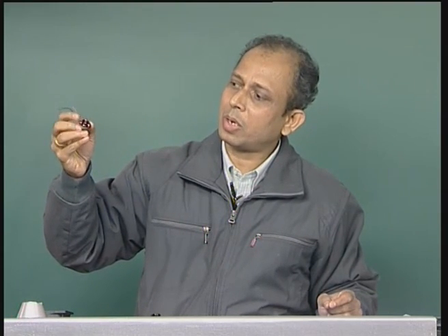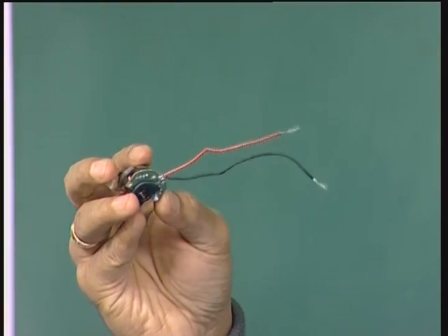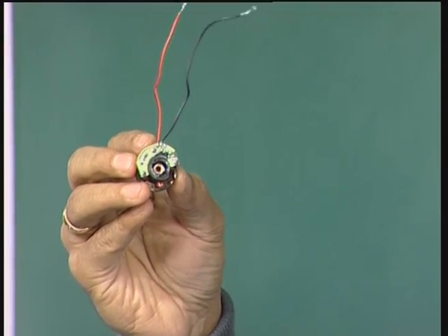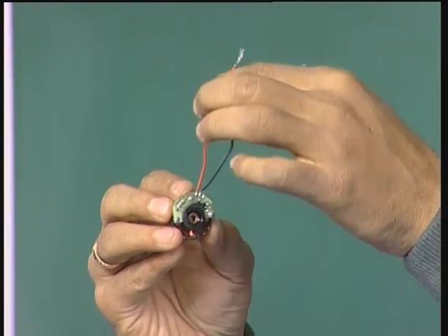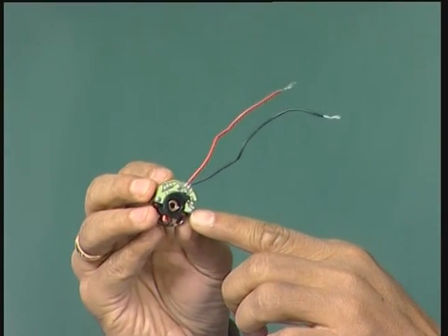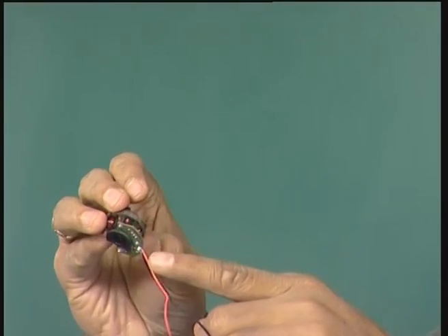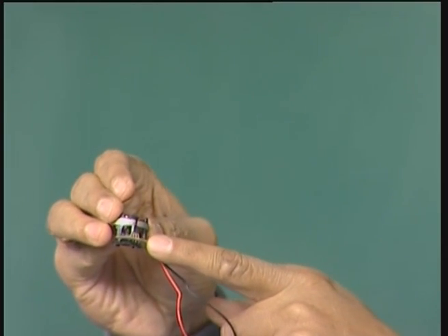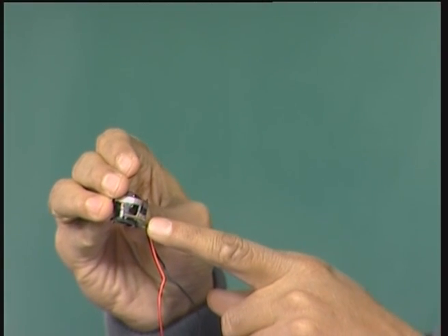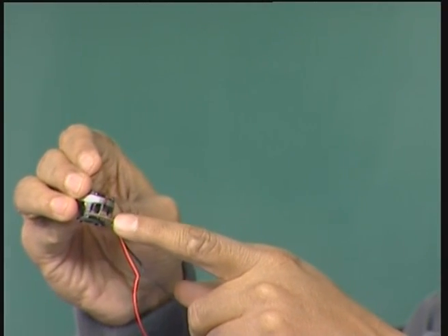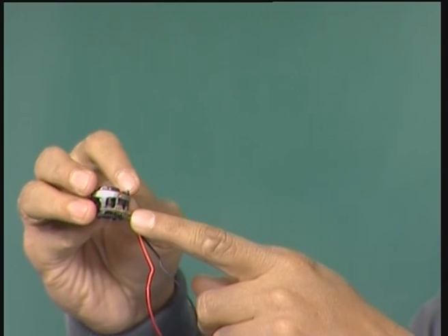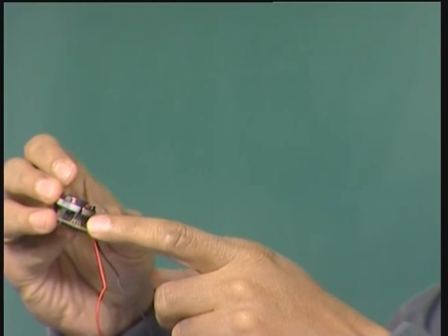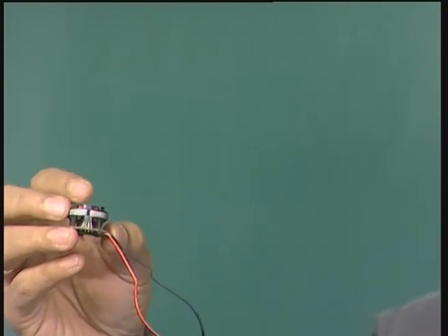And if you see very closely, there is a printed circuit board here which is attached to this stator. It is stationary and connected to the external power supply. So, this is the printed circuit board, and in the printed circuit board there are very few components. You can see there is a single transistor structure here, and this has got 4 legs. These 4 legs could be for the 4 windings. Since we have 4 windings, this basically is a power switch, and this will be switching the current to all these 4 windings.